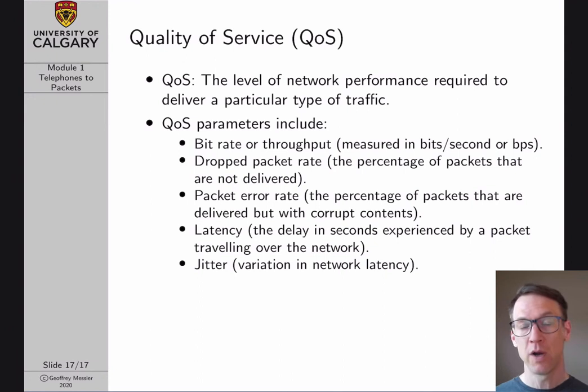And the bit rate required by different applications can really vary. HDTV, these numbers are a little old, but HDTV compressed using MPEG-2 requires between 19 and 38 megabits per second. Lower quality, older style Netflix video can run over 3 to 5 megabits per second.